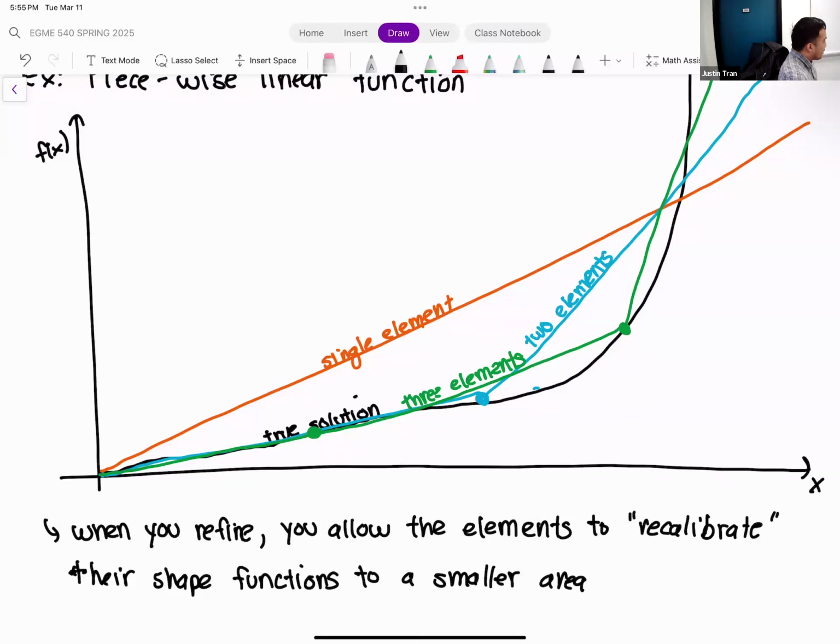Okay, so you want to be a little bit selective, because remember, refining your mesh doesn't come for free. Whenever you refine your mesh, you're adding additional elements to your simulation, you're adding additional costs. A unique barrier that you have in this class is that you get closer to that limit of elements that you can possibly have in the educational version of ANSYS. And so you want to be selective with this. That's why, for this part, I want to be very careful and say this is a local refinement. This is not something that you're applying to the entire mesh.